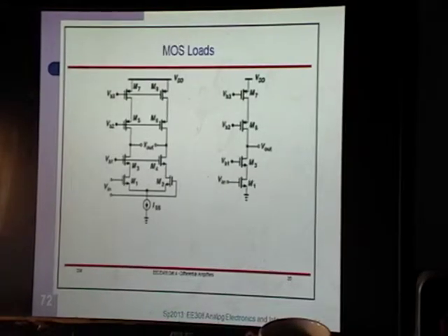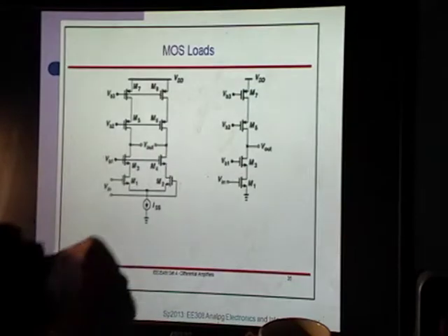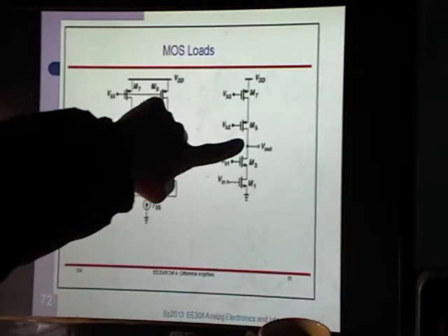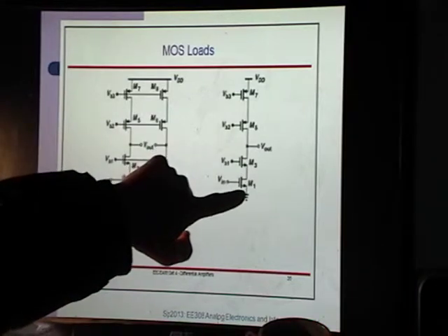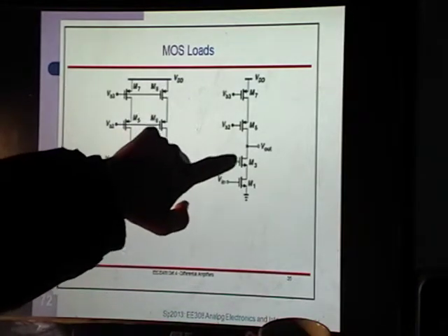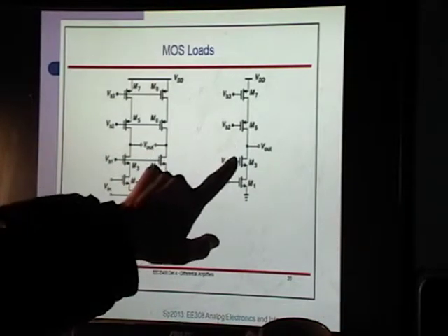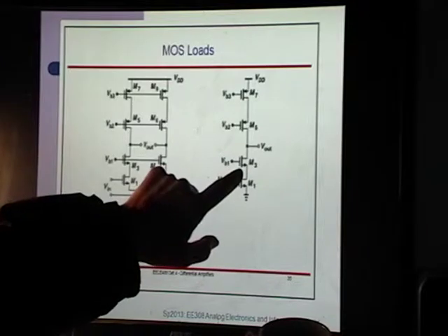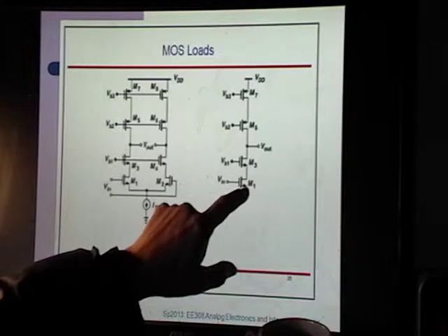Okay, so cascading is good for low voltage, but this video is about cascoding, with an O. Not cascading. Cascading is where you string the amplifiers together. Cascoding is where you stack transistors together. You'd think that sitting on this V out and looking down, you'd see one RO and then another RO. But with cascoding, what you actually get is an RO squared. Well, for MOSFETs you get an RO squared. For BJTs you get an R pi times RO. So it multiplies instead of just adds.